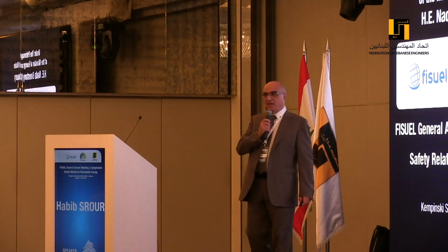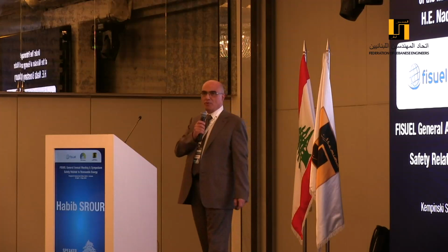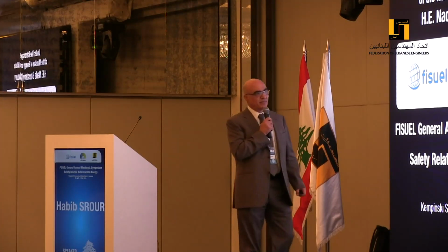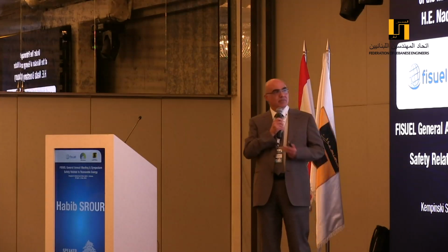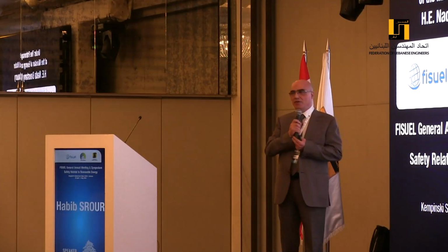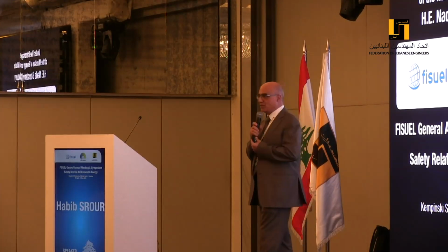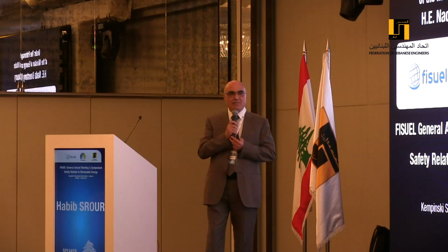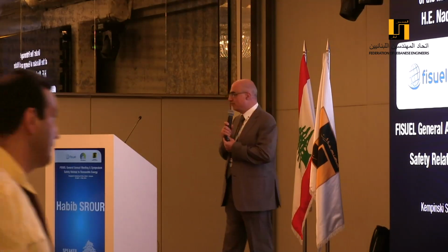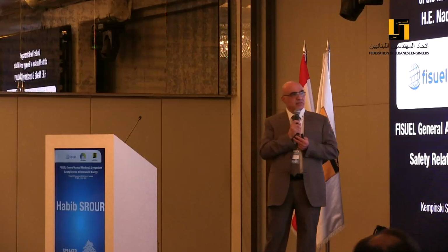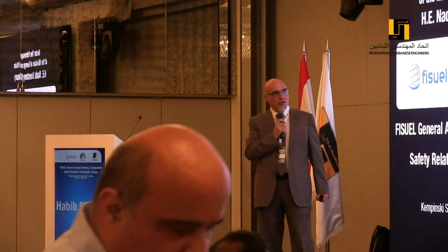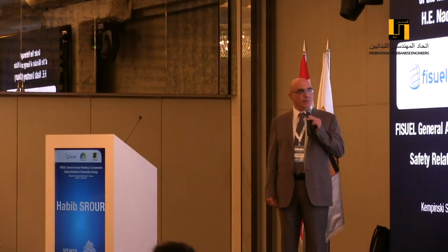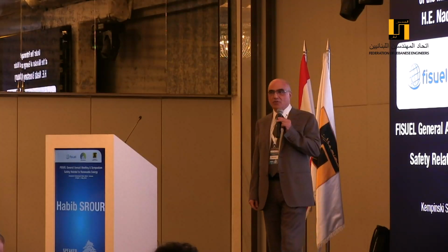In fact, any elevator nowadays is composed mainly of a rotating machine with a set of ropes laying on the pulley of the machine. The pulley of the machine is called, in lift terminology, the traction sheave. From one end, the rope is connected to the cabin, and from the other side, the ropes are connected to the counterweight.